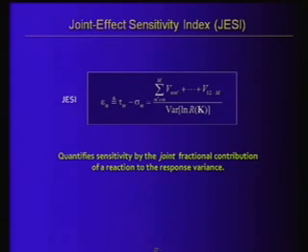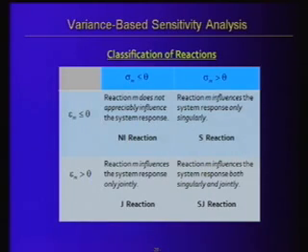So having these quantities, I can play a nice game that is described by means of this table. I can pick a threshold theta, which is a small number close to 0, user defined. If the sigma value of the mth reaction is negligible and the epsilon is negligible, then the reaction does not appreciably influence the system response. So I can classify it as a non-influential reaction.